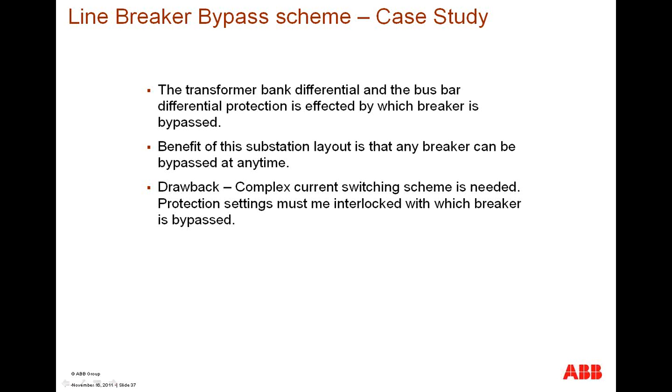All right, moving from the capacitor bank logic, we're going to look into another application called the line breaker bypass scheme. With this bypass scheme, the transfer bank differential and bus bar differential protection is affected by which breaker is bypassed. The benefit of this substation layout is that any breaker can be bypassed at any time. The drawback of this particular scheme is that a complex current switching scheme is needed. These protection schemes must be interlocked with which circuit breaker is bypassed.